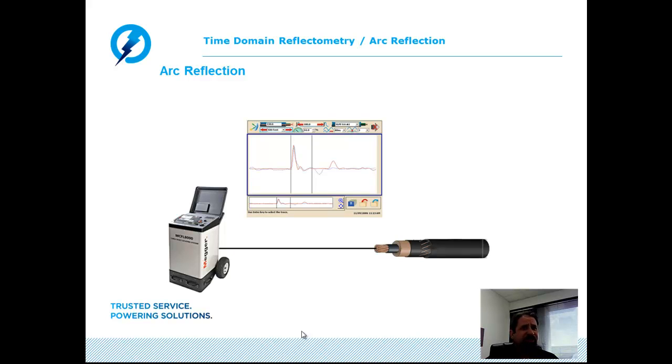A coupling device referred to as a filter or also referred to as a power separation unit is introduced into the circuit, allowing the high voltage surge generator and low voltage time domain reflectometer to be combined simultaneously to the faulted cable. The function of the surge generator is simply to transmit a high voltage surge into the faulted cable. This surge momentarily reduces the resistance of the shunt fault. During the high voltage impulse time interval, the pulse echo technique is applied using the time domain reflectometer.